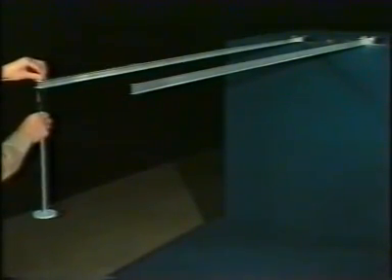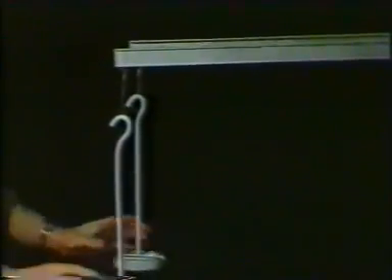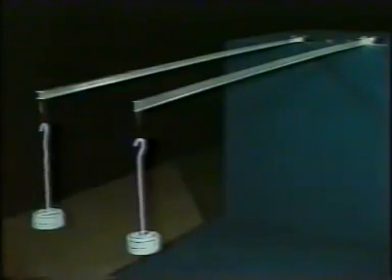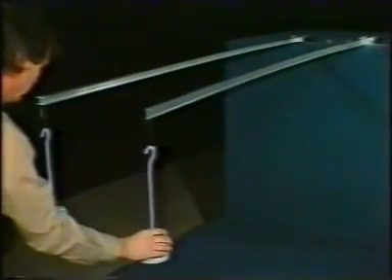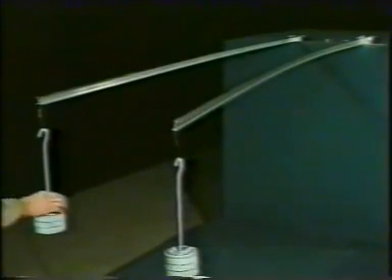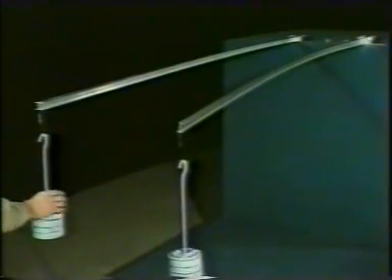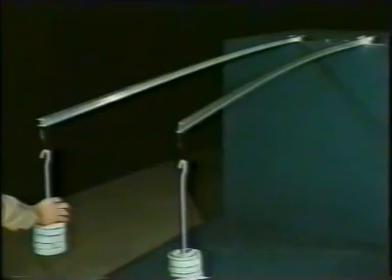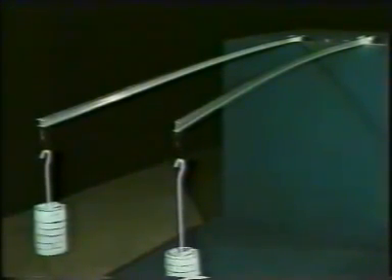Observe the response of the two cantilever beams which are of equal length and which have nearly equal major axis flexural rigidities. The one on the left has a high minor axis stiffness, whilst the one on the right has a low minor axis stiffness. Initially, as equal load is applied to each beam, their behaviours are almost identical. However, for the beam with low minor axis stiffness, as loading progresses, instability intervenes. The cantilever on the left does not suffer any instability and would eventually fail by plastic action. Lateral torsional buckling is only likely when a section has significantly different values of second moment of area and is subjected to bending in the stronger plane.